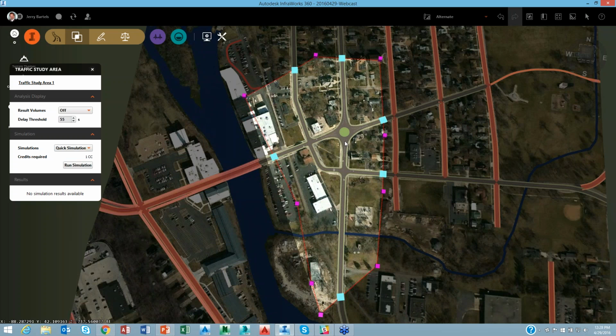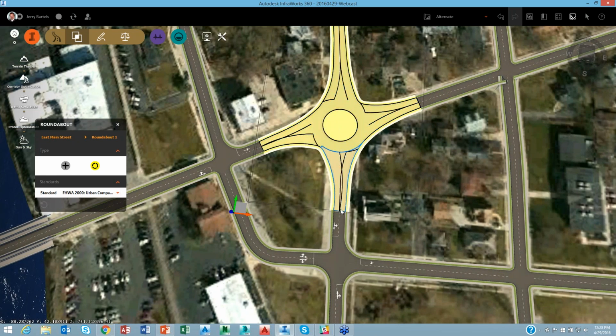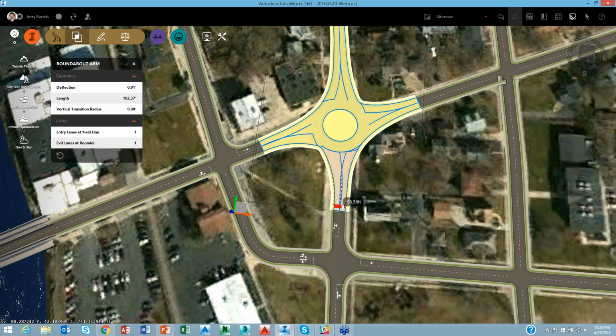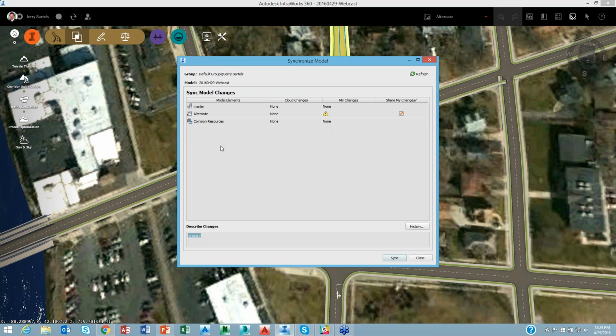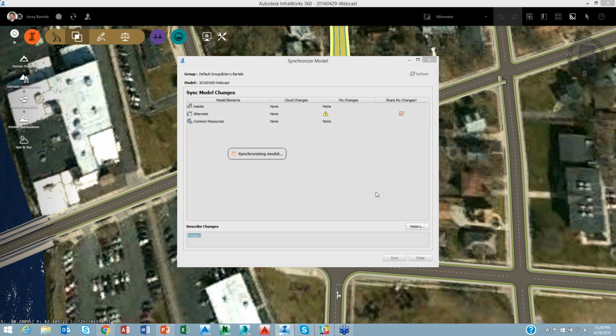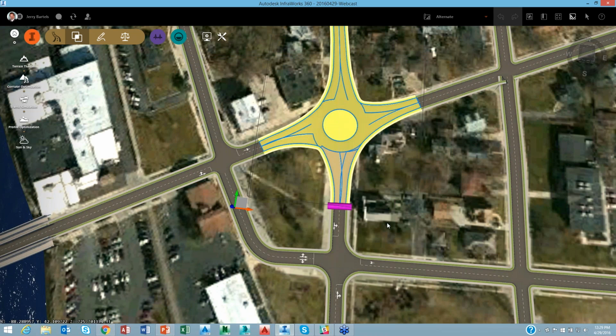Let's come back in. I'm going to go back into edit here. Make sure that I don't have something. My geometry will back him up just one more touch there. We'll close out of that and then sync this back to my project. Sometimes if my distances get pretty close, it can impact my analysis with respect to where the roundabout ends and where it starts back up again. So we'll make that quick adjustment.